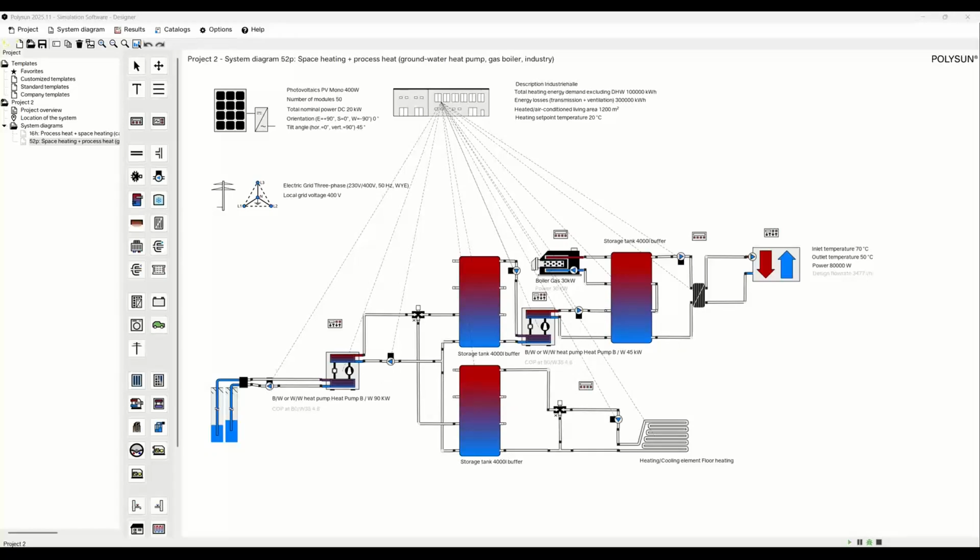So this Cascade heat pump system offers these two heat pumps here in series. The first heat pump uses the groundwater as a source and has a temperature difference of maybe 5 to 35 degrees. You can adjust it depending on your needs. And then the second heat pump, the booster heat pump in this heat pump cascade, can bring up the temperature from 35 to 70 to deliver the right temperature here at this energy